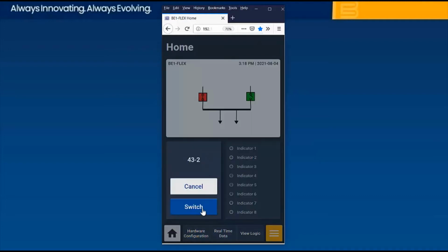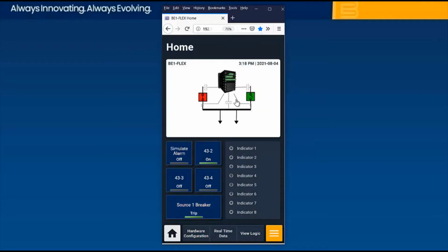This is just a basic example. I'm going to show what I've programmed into the HMI that shows the instrumentation. For this application, I'm going to be looking at the current transformers at this point and this point, and be able to summarize them together and also multiply them with this voltage to provide power readings, and use them wherever I want to use them, just as if they were direct measurements.